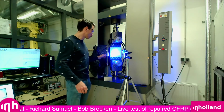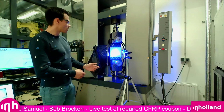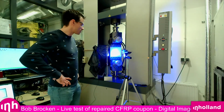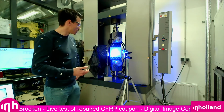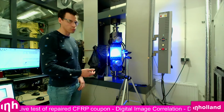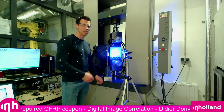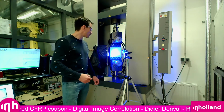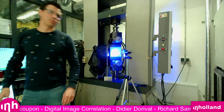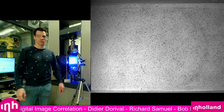the carbon fiber part. And then the rest of the setup is based on the DIC camera system, which Richard already explained, which tracks the displacement of a sample. In this case, it does that with about 3 frames per second. And we use a blue light to further increase the contrast between the white background and the black speckles. And if Ruben wants to switch to the 3-view system, then they can actually see the sample.